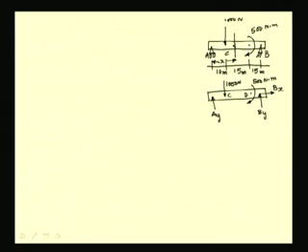Now, from this free body diagram, we can write three equations which can be used to determine the three unknowns. So, let us write those equations. We can write the force summation equation for the vertical component. So, we have the force Ay, the force By, the two unknown vertical reactions, and the vertically applied load which is downwards, equal to 0.